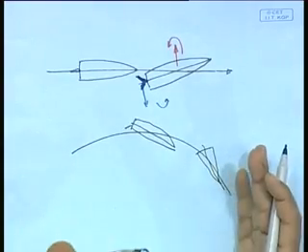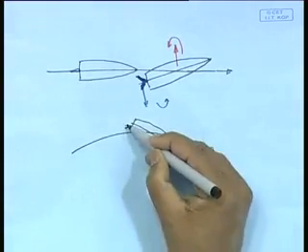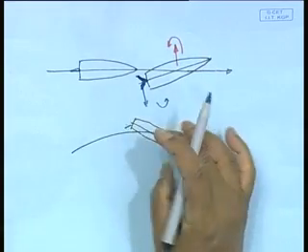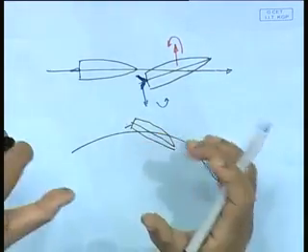Now what does the force consist of? Remember, I have a rudder force, I have a hull force. So as I give rudder, my hull would have turned and would have balanced at such a location that my hull force and moment balances the rudder force and moment.